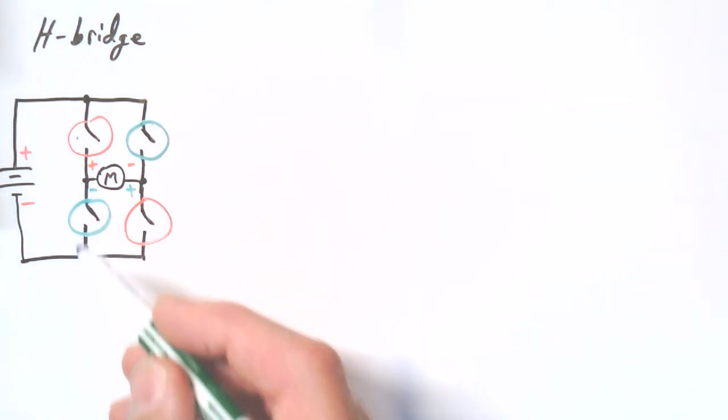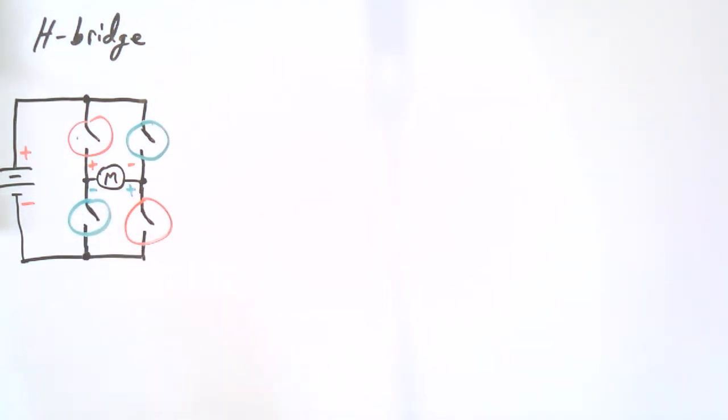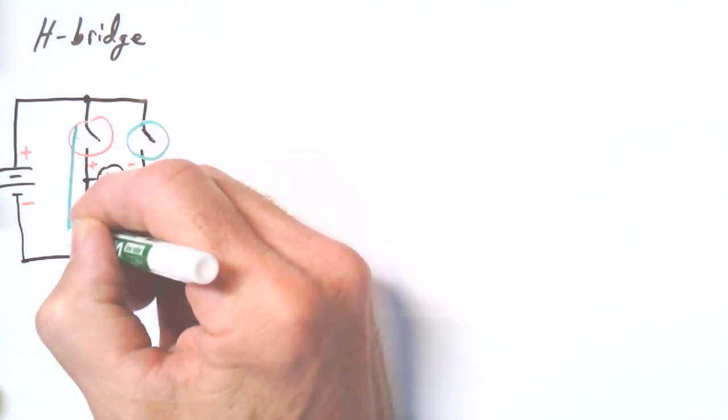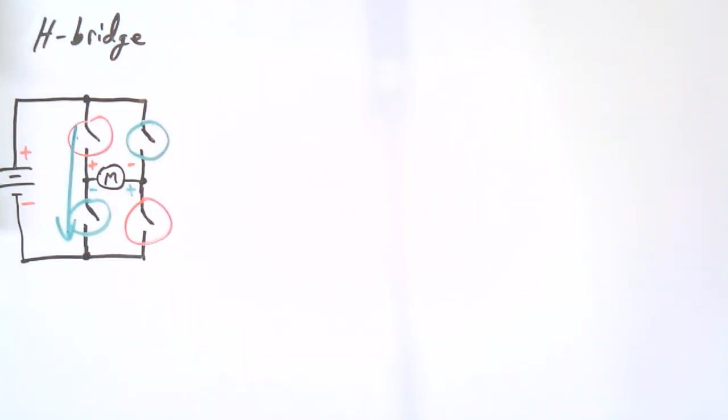It can happen that they're on for a brief second, split timing, and then you get what's called shoot through, which is current running down through the transistor. So it can be a little tricky with the transistor thing. If you give it one command and one has to go off at the same time one comes on, you have to watch out for that.